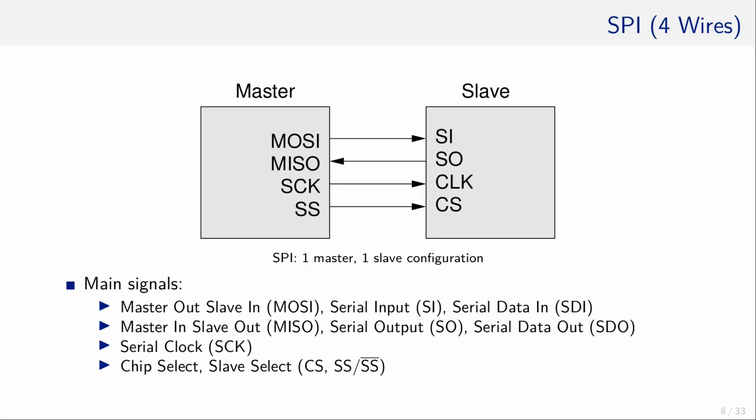How do you connect those? As you can see, MOSI is an outgoing connection from an SPI master to an SPI slave. Therefore, MOSI stands for Master Out Slave In. That MOSI signal is connected to SI, which is the abbreviation for slave in. Similar with MISO, which is the short form of master in slave out. It is there to receive data from the slave out pin.